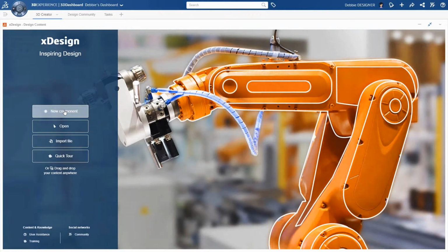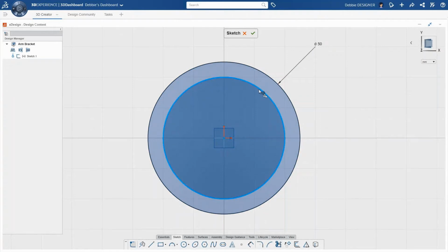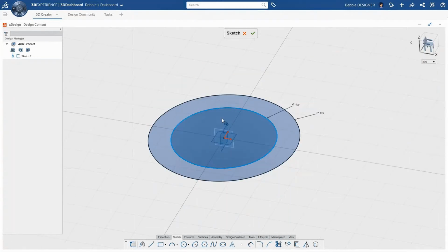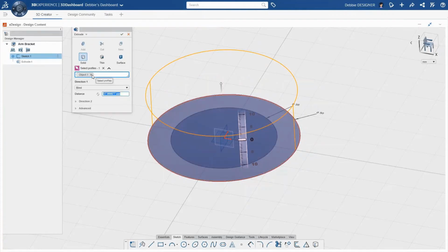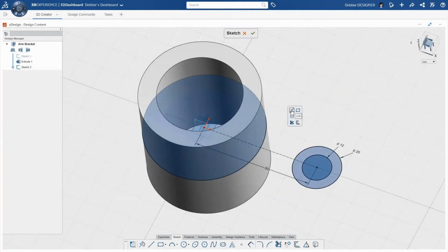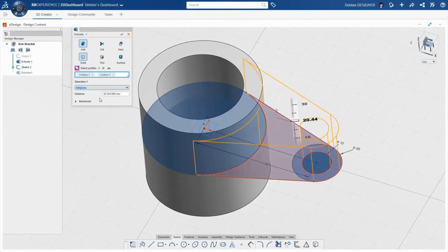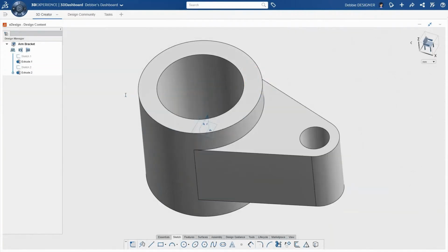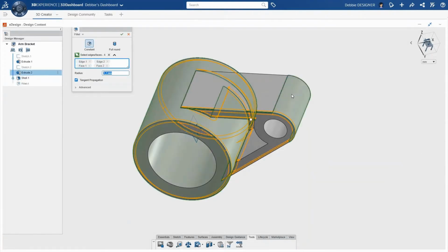She's going to use the xDesign app in 3D Creator to create a new mounting arm bracket for the monitor stand. So working totally just within her web browser, she's now got access to actually creating geometry, starting a brand new design. So she's starting with the core part, the central part of the bracket there. So just using a sketch-based approach, sketching out the profiles, building in some symmetry, and building in the whole shape, so she can just choose which contours to extrude to create the geometry. So it's a really quick and easy way to go ahead and start building up the design.